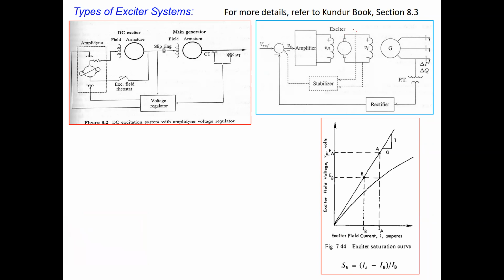So I mean to say, what is the field current over here? And then what is the voltage? We get it here. So that means this is your field current, and what is the open circuit voltage here, right? So here on this x-axis, it is the field current, and then on the y-axis, it is the open circuit voltage. So what is the relationship? How does the open circuit voltage vary as you vary the field current? So this is what is shown here, right?